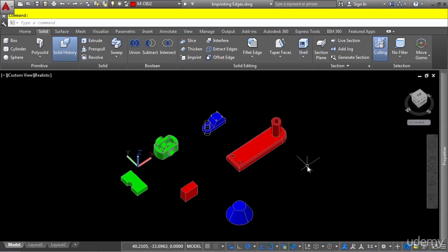When you imprint a solid model, you are either scoring the face with a geometry or splitting the face in the solid model into multiple faces. For the geometry to imprint onto the face, it must be coplanar with the solid model face. As you design your model, you will have instances where you have a single model surface that you would like to edit in different areas. By splitting the face, you can perform other edits on the smaller face area, such as tapering, rotating, or moving a section of the face.